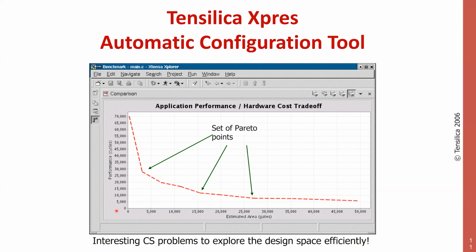So you have two criteria here. You want to maximize performance or minimize, actually this is not performance, but it's time, right? Minimize runtime. You want to minimize the area in number of gates, complexity. And so something is Pareto optimal if there is not another point that is better in both respects, because if it has better performance and it has better area, clearly this point is not good, this point is good and is interesting, right? So this is a Pareto optimal point.